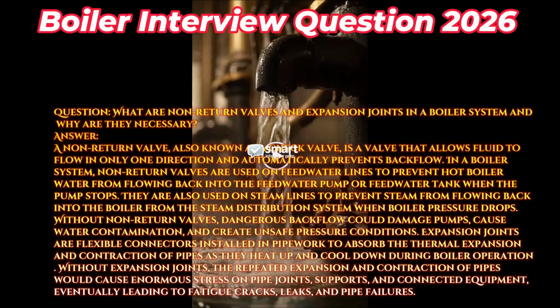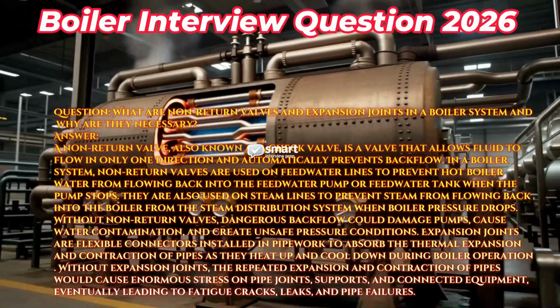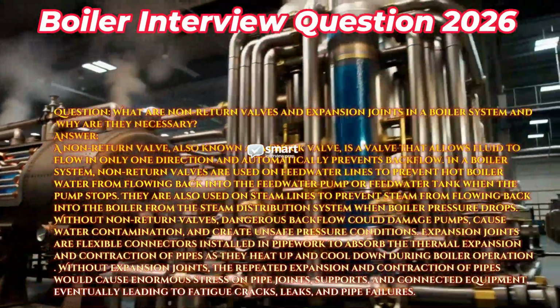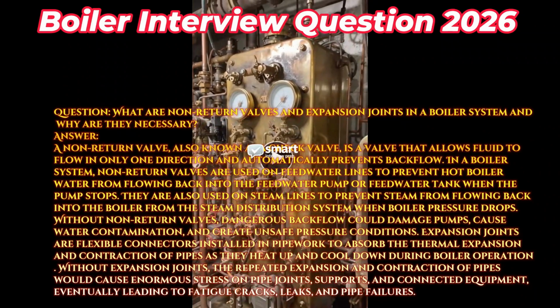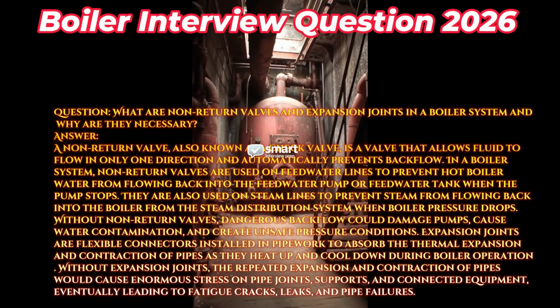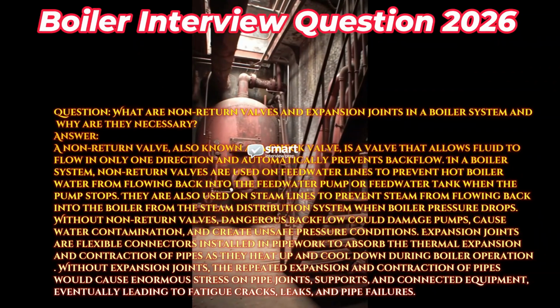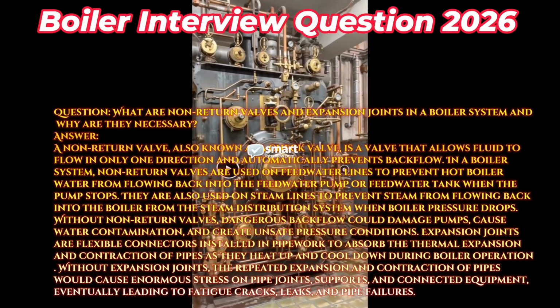They are also used on steam lines to prevent steam from flowing back into the boiler from the steam distribution system when boiler pressure drops. Without non-return valves, dangerous backflow could damage pumps, cause water contamination, and create unsafe pressure conditions. Expansion joints are flexible connectors installed in pipework to absorb the thermal expansion and contraction of pipes